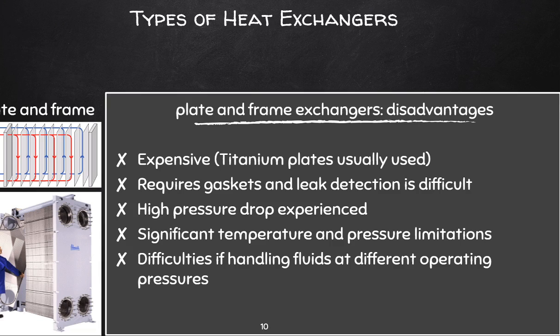The plate design is not a good shape to resist pressure, especially differential pressures. On one side of the plate will be one fluid, on the other side of the plate will be another fluid. If there's any pressure difference between these two fluids, it can buckle the plate. And obviously the maximum operating pressure is limited to about 30 bar, where a pipe can go up to 500 bar.